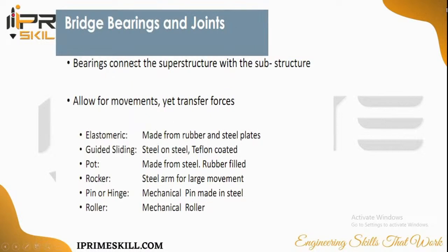Now we go for the bridge bearings and the joints. So what is the purpose of giving the bearings? Bearings connect the superstructure and the substructure. Why? It allows for movements, yet it transfers the forces.